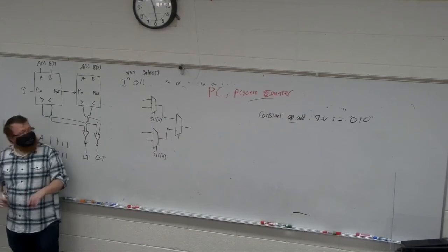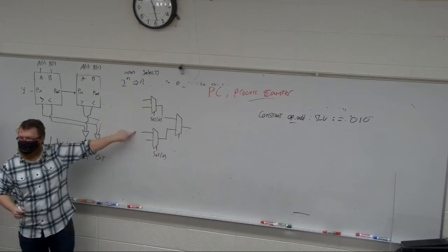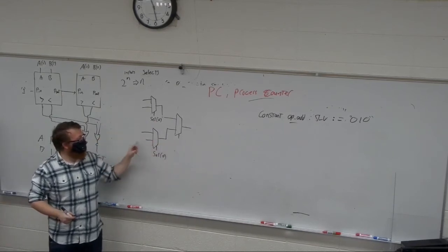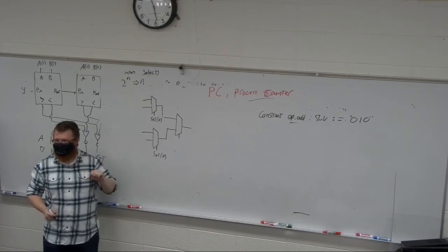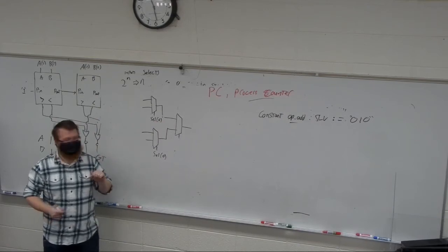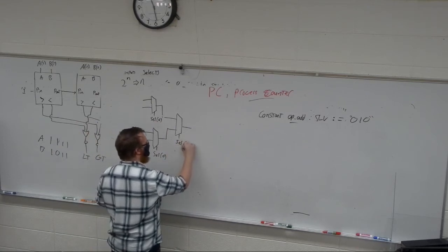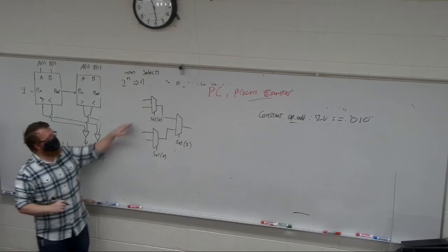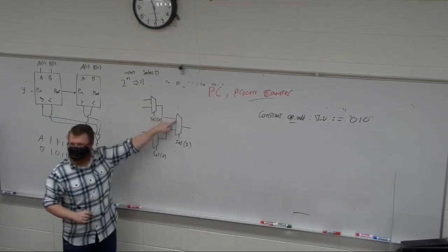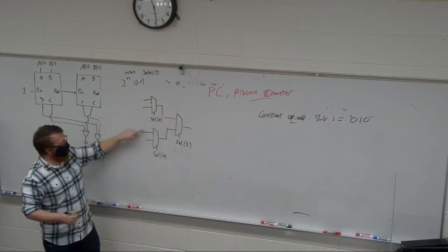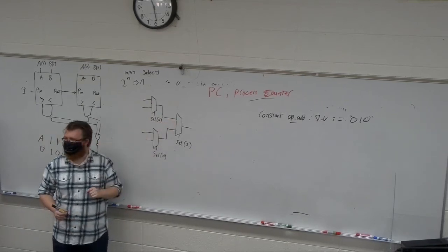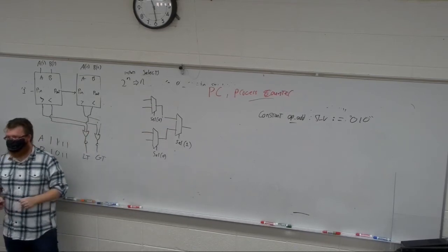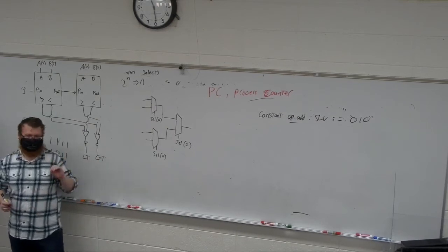So the first bit says it's going to be either this one or that one if it's 0, right? Then this one will choose top or bottom for us. So now 0, 0 is 0, 0. 0, 1 is 0, 1. Now, using this architecture, we can access any of our inputs based on the select.